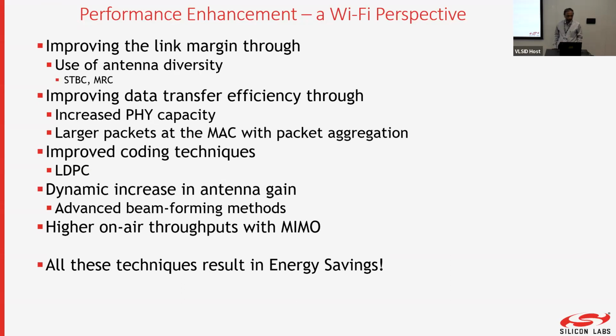Then you can use beamforming. That means you can use multiple antennas, and then you can combine the antennas with a certain phase so that the antennas point to a particular direction. When you have two antennas combining the signal, in one direction, the signal of one antenna may be 180 degrees out of phase with the other, because that's equivalent to half the wavelength. So if it's 180 degrees out of phase, it subtracts. So you get a null. If it is 0 degrees out of phase, you add. So that's why antenna arrays have a certain directionality. And you can use beamforming with multiple antennas.